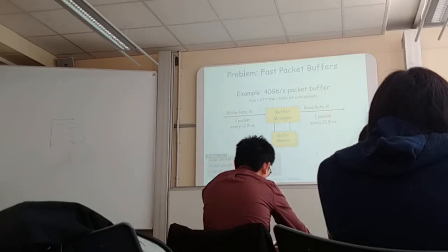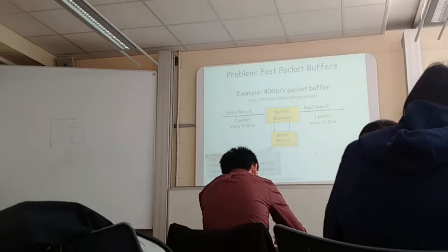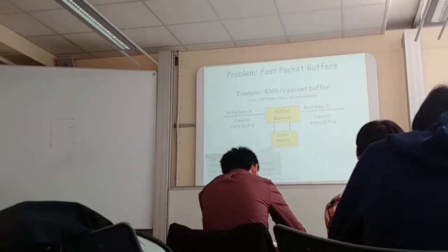And now the question is, for a router engineer, what type of memory would you use there? Now we talked about static random access memories, SRAMs. They are known to be fast for this time. They could cater for that time. The problem with SRAMs, they are too low density to store 10 gigabits of data.